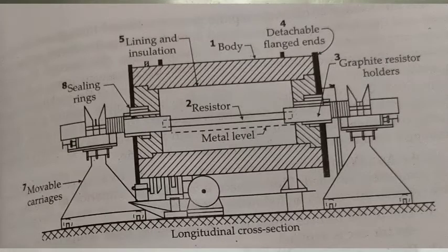It consists of a cylindrical shell with detachable flanged ends. For ease of lining, the furnace is designed to rotate on rollers, and the sixth part is to enable the body to be rocked backwards and forwards. The refractory lining shown by point 5 is built into the shell. To reline the furnace, the shell is lifted off, the rollers are turned vertically on the end, the top end cover is removed, and the lining material is rammed round suitable formers.